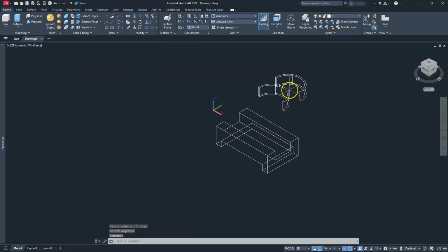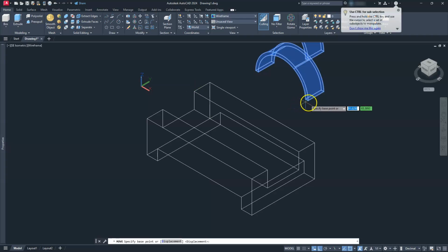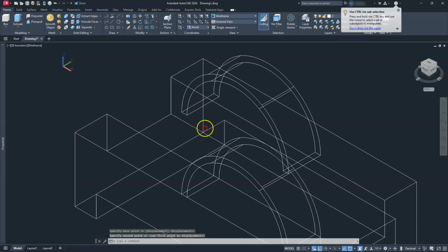Next, I'll go ahead and stand these two up. So I'm going to select both of them. Let's go ahead and switch over to the rotate gizmo. Select the red axis, and then click here. Now I need to just move these in place, so I'll move the first one here. I'll go from that end point here to here, and then I want to move this one, right?